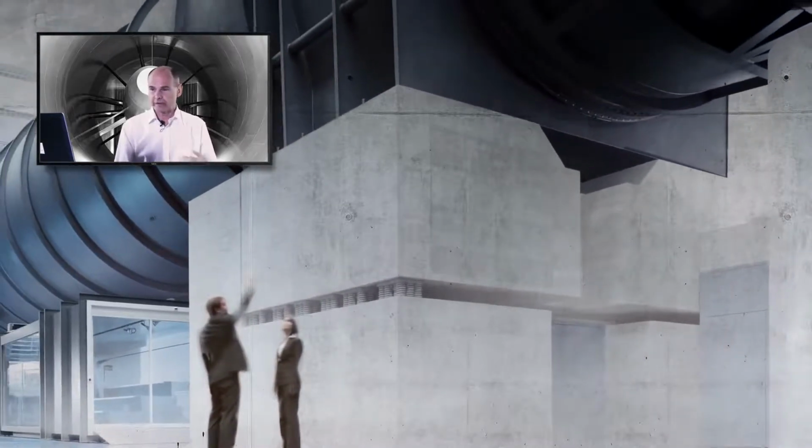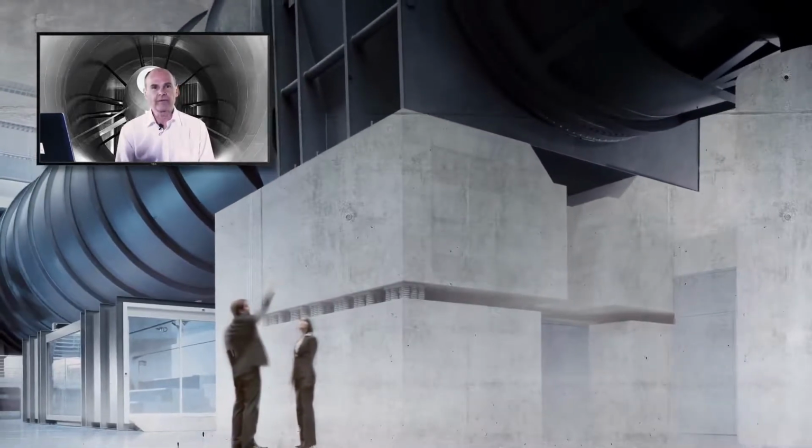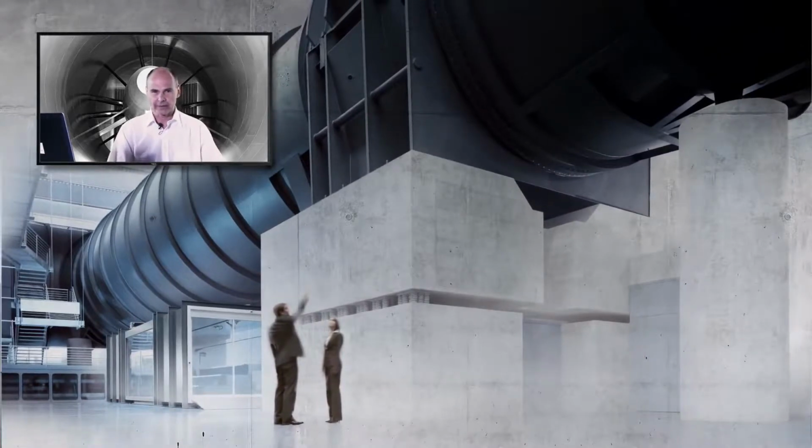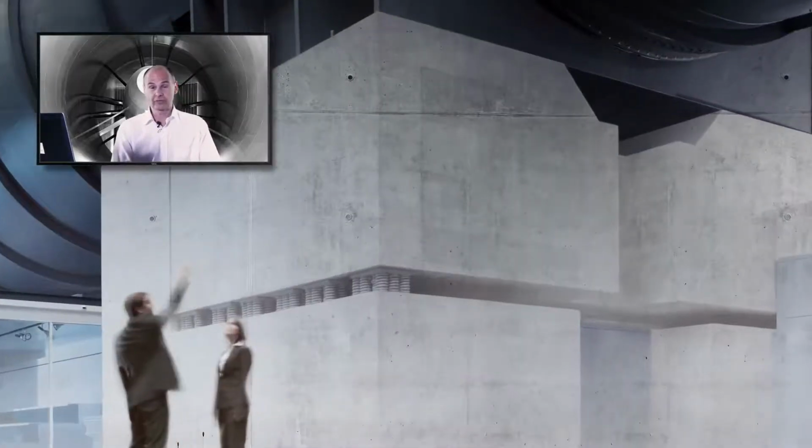The reason is that if you didn't have it mounted on something very, very solid, it would create a seismic event, an earthquake, because you're using so much power. And no matter how good a job you do with your fan, it'll never be perfectly balanced. It'll be reasonably well balanced, but it's never going to be perfect. So you mount it on a very large mass, and the seismic mass is then mounted on an even bigger mass via, literally, springs and dampers.